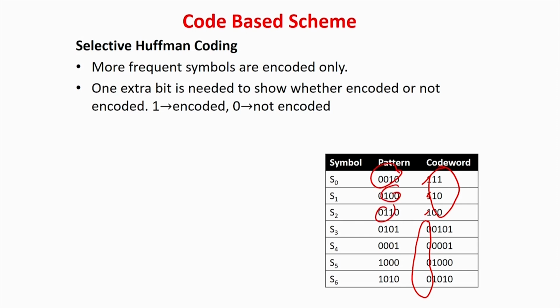The gain is that your decompressor circuit inside the CUT will be of smaller area. But what is the cost you are paying? Certain patterns which are rare will take a higher channel width from the ATE, so the cost will rise, but not to worry that much, because they are very rarely occurring patterns.